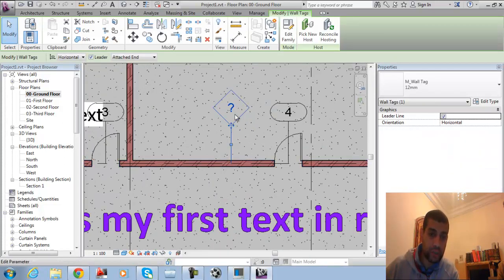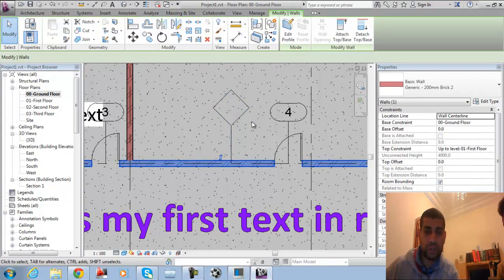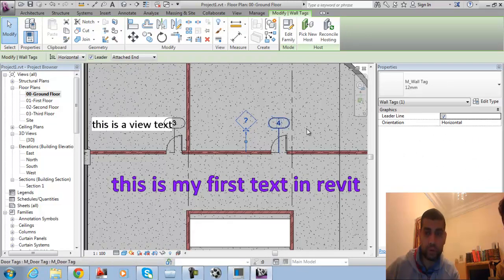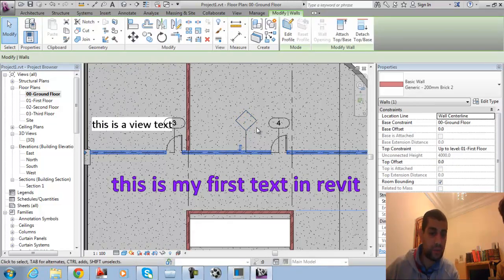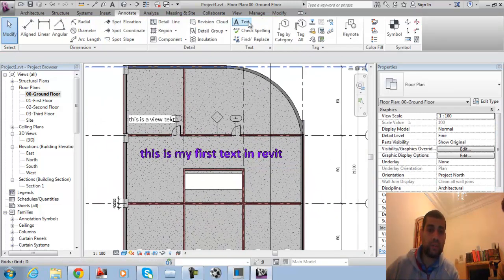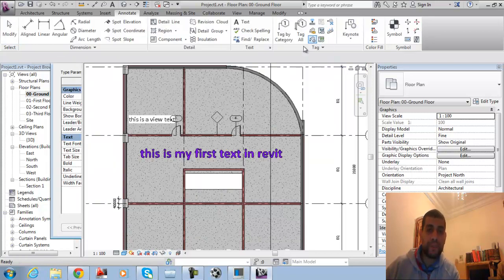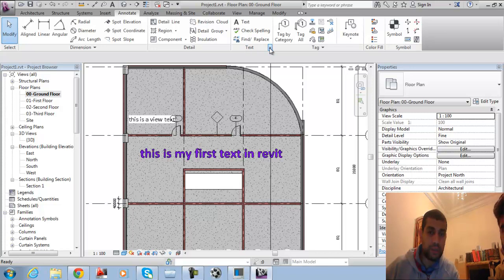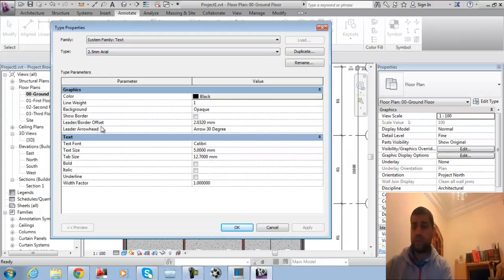Also, there's no information here because we don't have information for this wall type. Okay, or we don't add information to be read from this wall. Okay, Fayaz? So the text, you may add text. This text comes from annotation, just a text belonging to the current view you are writing in. Okay. Look, if you see any arrow like this aligned arrow, that means it brings up a dialog box for you.